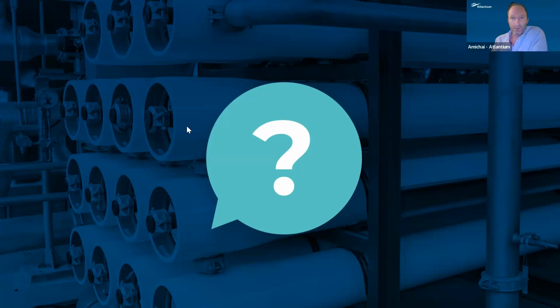Next one: in case the municipality is providing water with monochloramine, which we see quite often, can UV be used for dechlorination of the monochloramine? We haven't discussed it in the presentation, but this is monochloramine destruction using UV. Itzik, you want to address it? Yes. Monochloramine coming from the municipality we see mainly in the USA, or if someone is using RO for treating municipal wastewater coming from the facility. If it's coming from drinking water, please note that municipalities send monochloramine about 11 months a year and switch back to free chlorine for 1 month. This is important to know. Monochloramine requires higher energy; for decomposing the monochloramine, higher energy is needed.